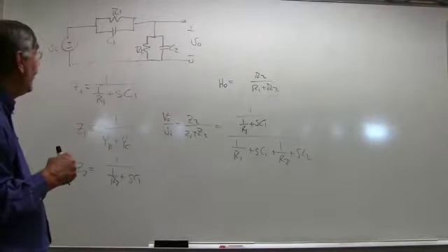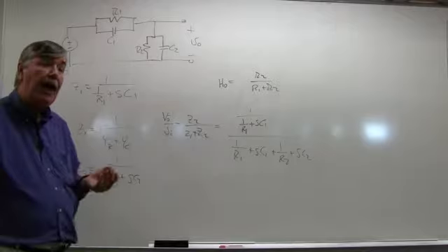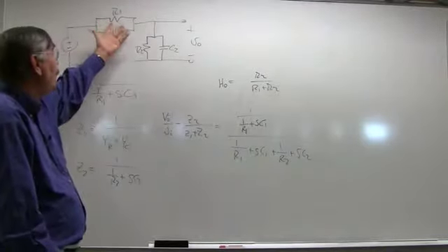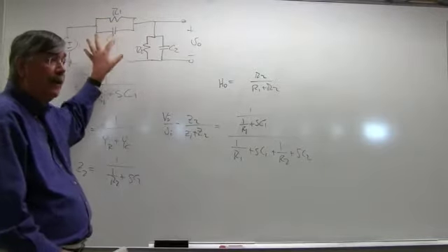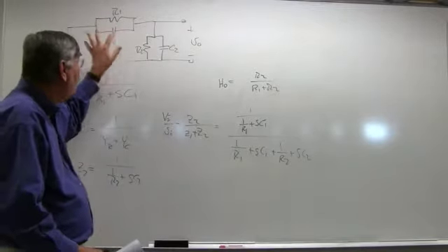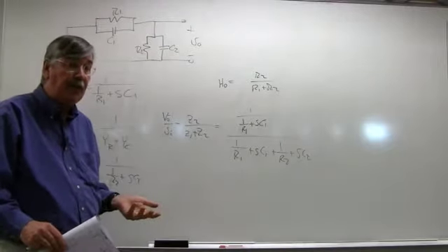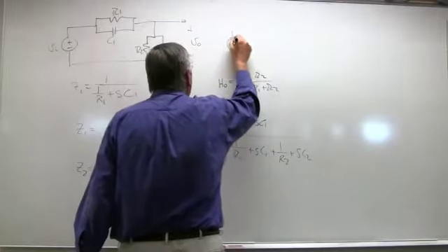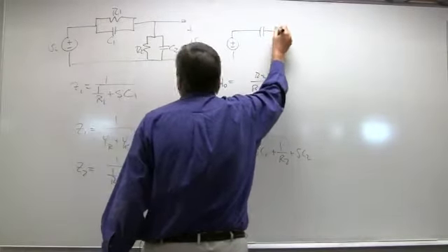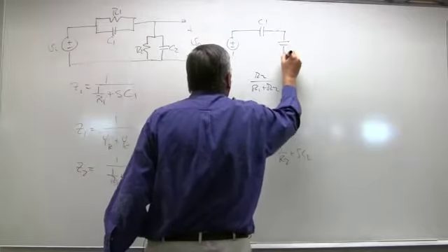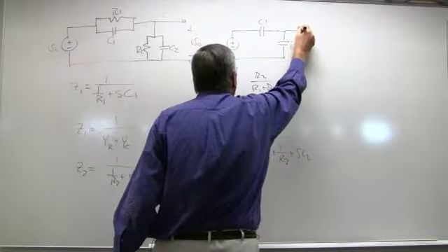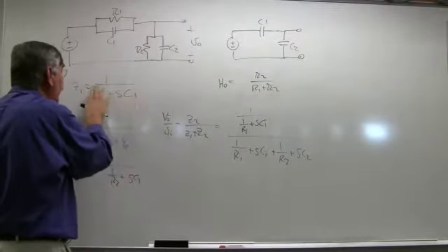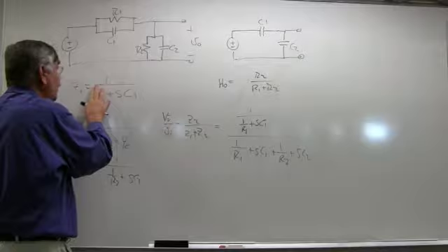What I really should have done, I think, another way to do this, is to go to high frequencies and make another voltage divider. At very high frequencies, compared to the capacitors, the resistors look almost like open circuits at a given frequency. At high frequencies, this whole circuit looks pretty much like C1 and C2, because the parallel combinations are completely dominated by the capacitors, and the Z's just look like the inverses of the capacitors.